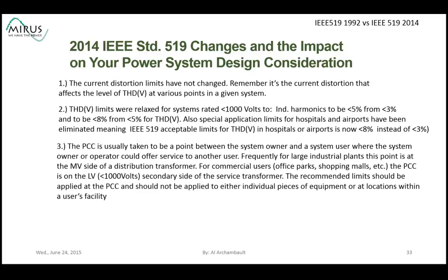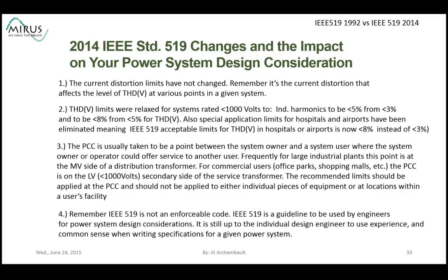The PCC is usually taken to be a point between the system owner and the system user, where the system owner or operator could offer services to another user. For large industrial plants, this point is at the medium voltage side of the distribution transformer. For commercial users such as office parks and shopping malls, the PCC is at the low voltage, secondary side of the transformer. The recommended limits should be applied to the PCC and should not be applied to either individual pieces of equipment or at locations within a user's facility.